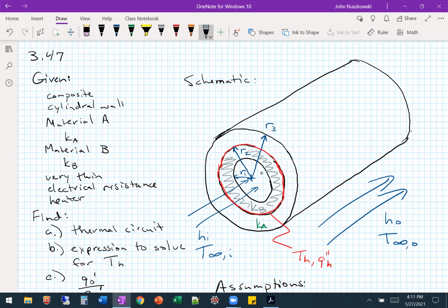From the center, from here? Yes. That's convection. So it's convection from that point out to R1, and then R1 to R2 is going to be conduction? Yep. Okay. I thought there was going to be an extra form of conduction happening in there, but okay, that makes sense. Yeah, it's a tube with moving fluid through the center. So that tube then has a T infinity to it, that fluid. Okay. Thank you. This is our material A.